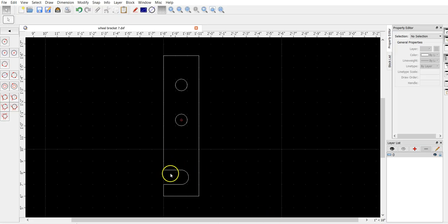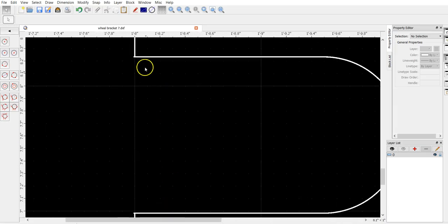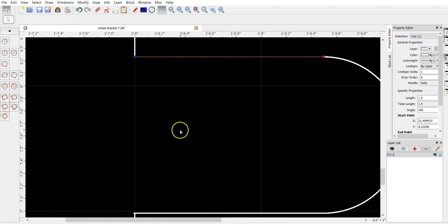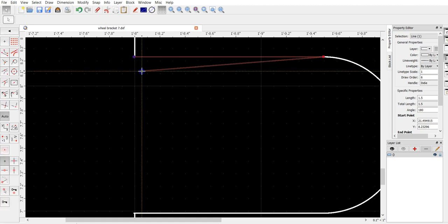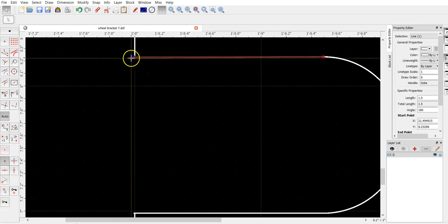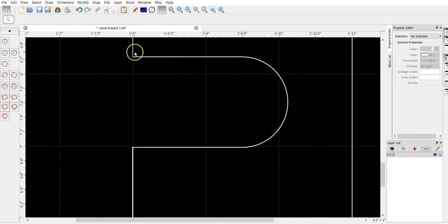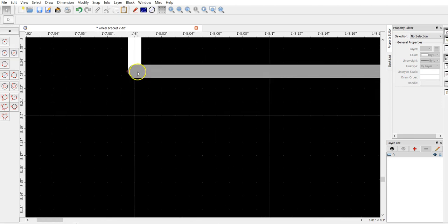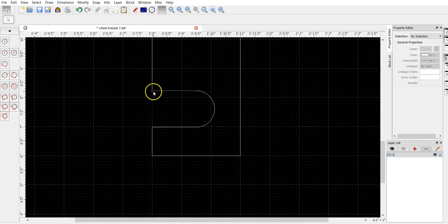We're going to go into QCAD here, and I'm going to go down to this bottom here. What I'm going to do is click on the line here, and I'm going to click close to, but not actually, I can probably grab this red piece here. Yep, I clicked and dragged on the blue line here, and I'm going to find this intersection point and click on it. That should bring my end to the end of this line.